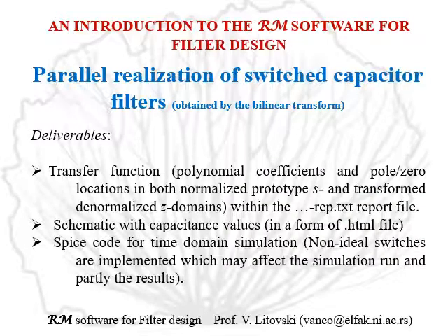This program delivers a report file which is following the complete synthesis process, starting with the poles of the original analog filter, then produces a HTML file which contains, in addition, schematic, all the cells which are implemented, including the summing and including the anti-aliasing filter and sample and hold filter too.